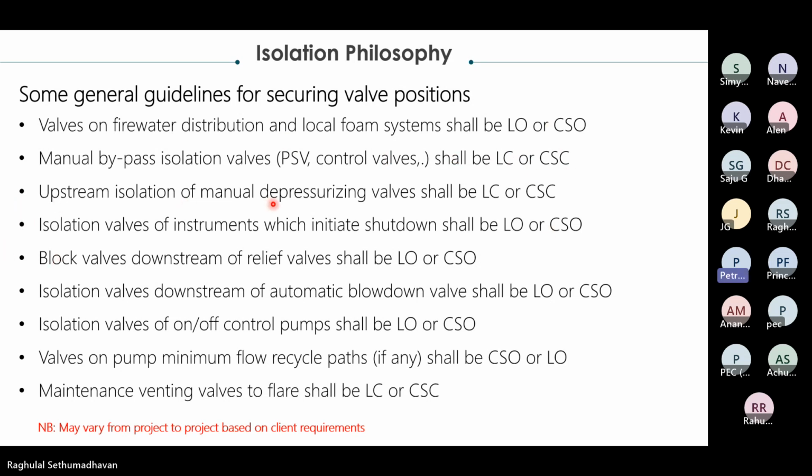Upstream isolation of manual depressurization valves shall also be lock closed or car seal closed. Isolation valves on instruments which will initiate shutdown, that is ESD initiating instruments, will be kept in open condition, either by lock open or car seal open.